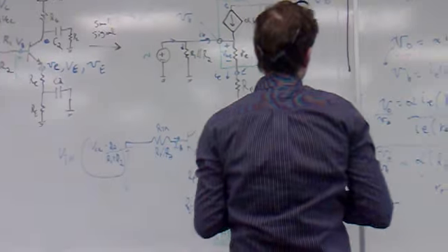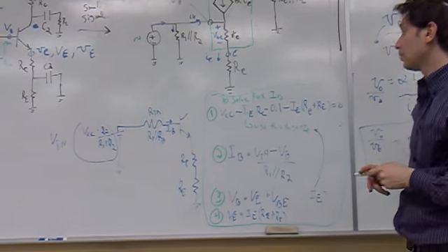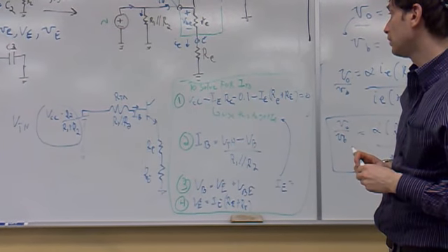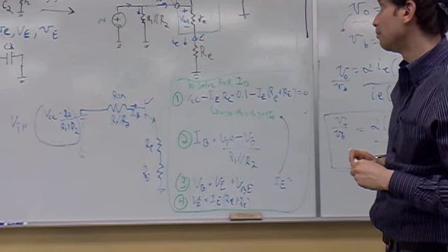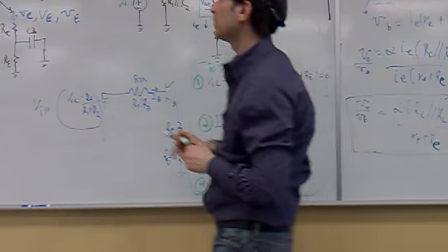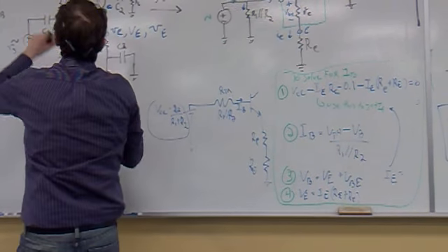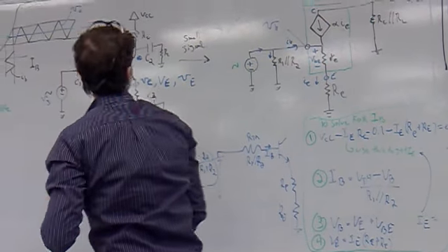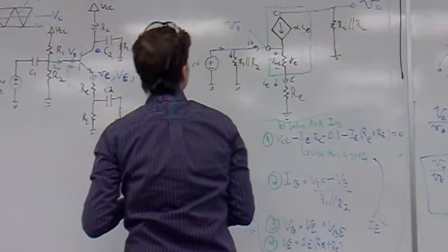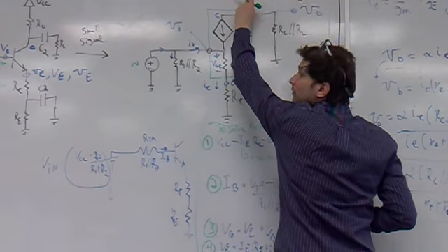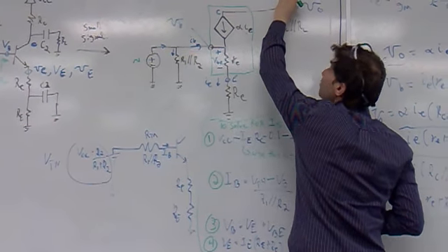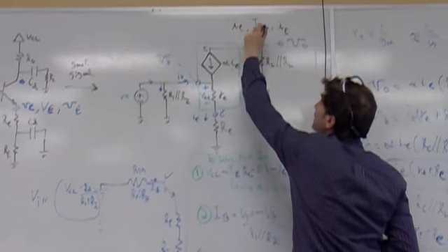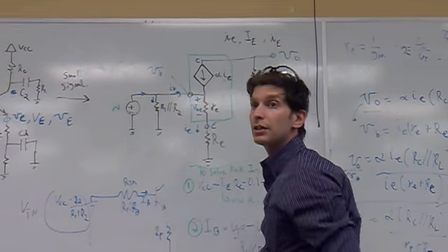That is it. So, last thing we're going to talk about is if I'm asking you to solve for the base current, the DC base current. We're talking about this base current going in here. I capital B. Do you guys know the difference between I capital B and all that stuff? Little i, little e, small signal. Little i, big E, combined, total, combined. Big I, big E, DC. Very good. You guys get that?